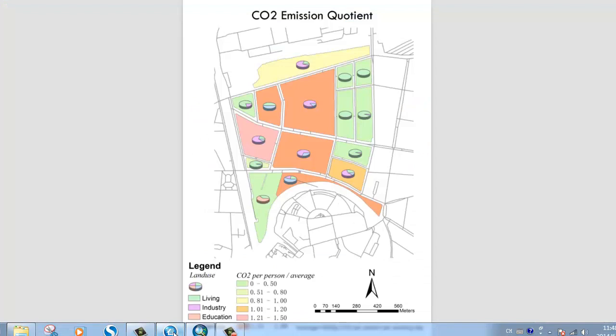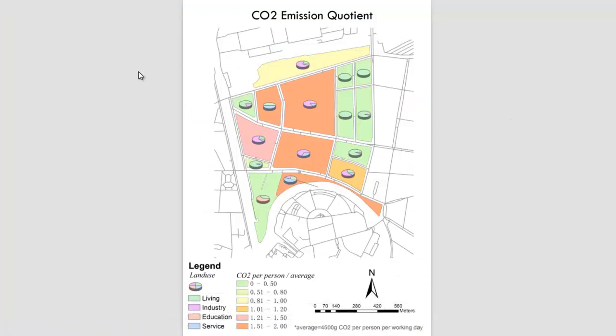The generated map shows a possible visualization of the results using the standard classification and symbology tools provided by ArcGIS on the example of a neighborhood in Berlin. This example shows the traffic-based CO2 emission in the area and the land use. It helps to find reasons for CO2 emissions or to evaluate urban and transportation concepts.